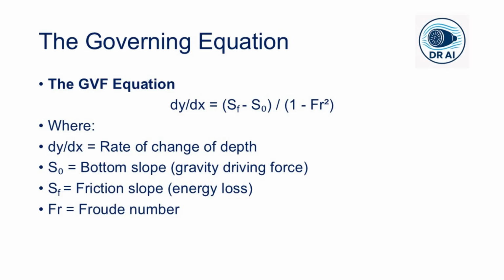So we have the key understanding of GVF in a single powerful equation, which is represented over here as dy/dx = (S_f - S_0) / (1 - Fr²). This equation might look intimidating, but it's actually a beautiful synthesis of everything we have learned so far. So let us break it down piece by piece.